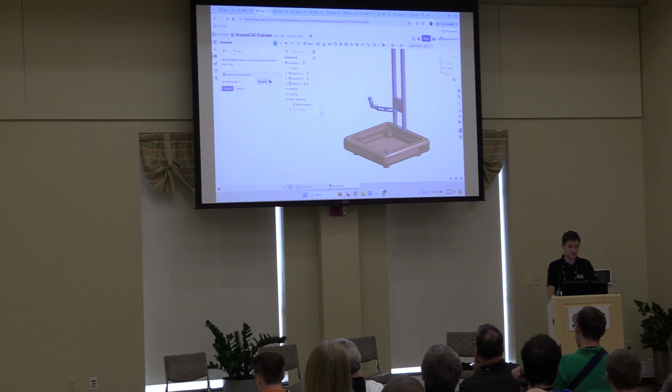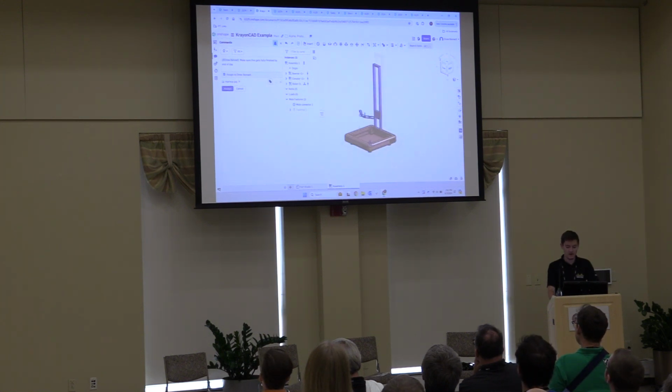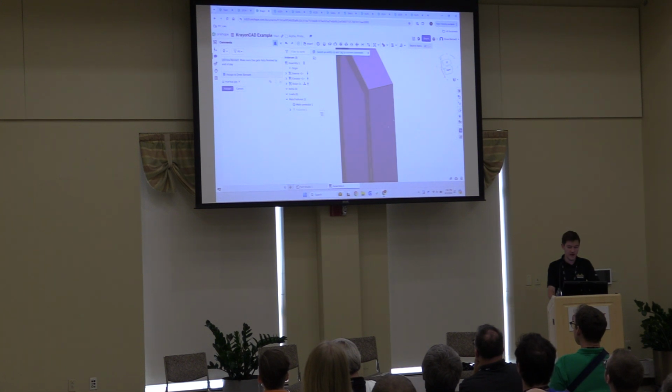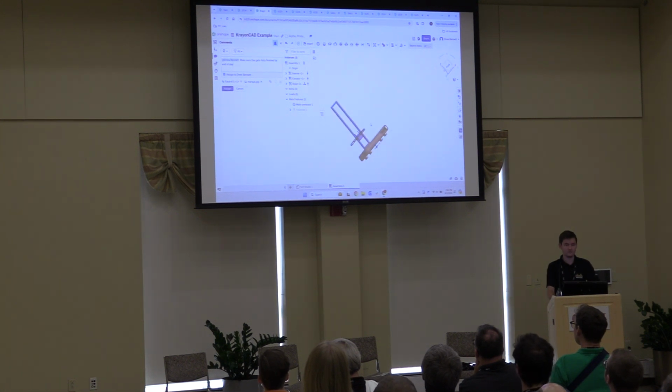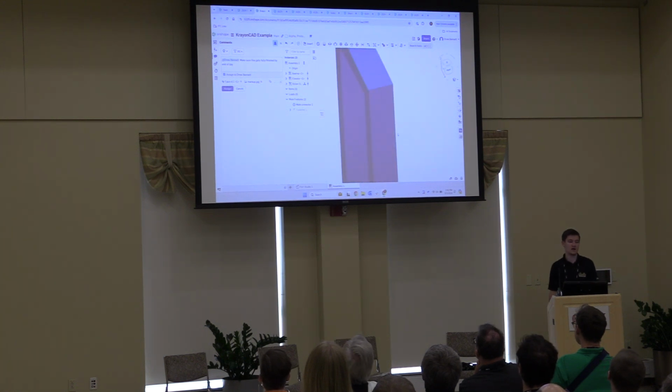Another one that I'll show you is tag entities. So this is really nice. Let's say you see something in the design that's not going to work. You can tag a specific part. It's cool too because if you zoom way out and you're lost in space, you can actually click on that and it's going to zoom you back into exactly where you were when you saw it. So if there's a very specific angle you have to be looking at to see that a bolt clearance is going to hit your intake as it goes by, you can make sure that everybody else is also able to see that. So Onshape does have some pretty solid communication tools built in.